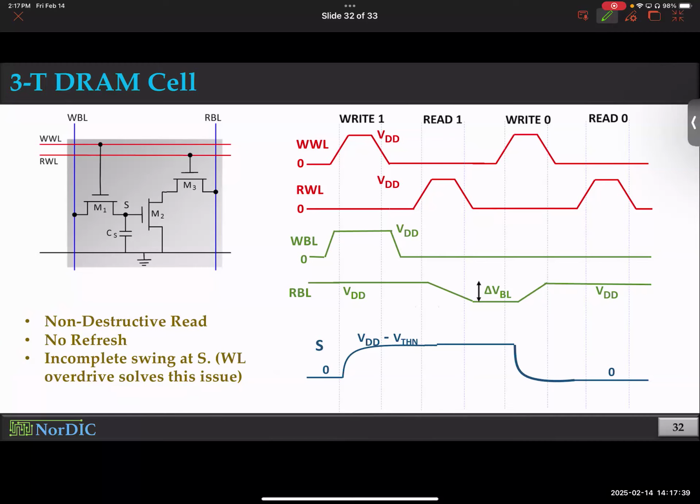By the way, remember, let me start with the argument with NMOS and PMOS. Yes, for some things NMOS will be good, for some things PMOS will be good. They both have limitations. For example, in one case, one will be very good at restricting discharge, but the same one will be very bad at bringing in additional noise. So it will not let the capacitor discharge, but it will introduce additional noise, for example. So in one way or the other, there is no perfect choice until and unless you use both.